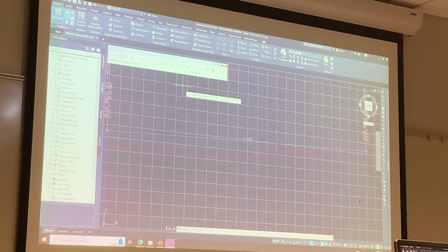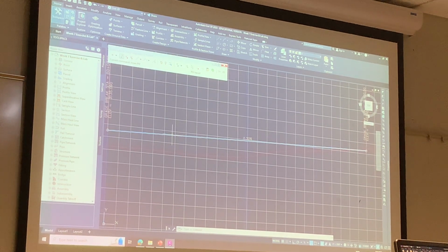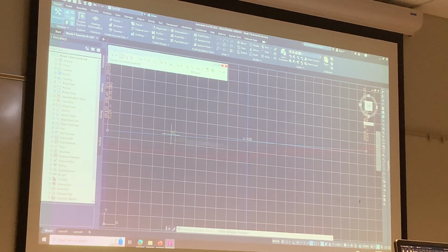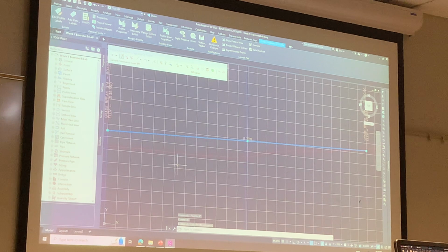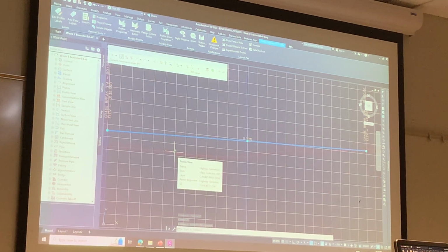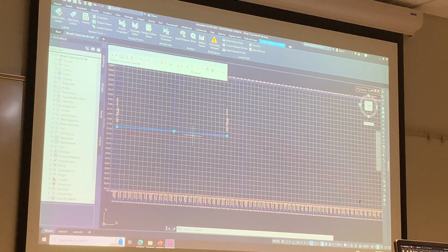Make sure that if you have your alignment profile drawn, you select it, and then right click and edit profile geometry. Okay. I actually deleted that because I couldn't find it. Okay, got it. Yeah, I'm there. I got it. Okay, so you're here.